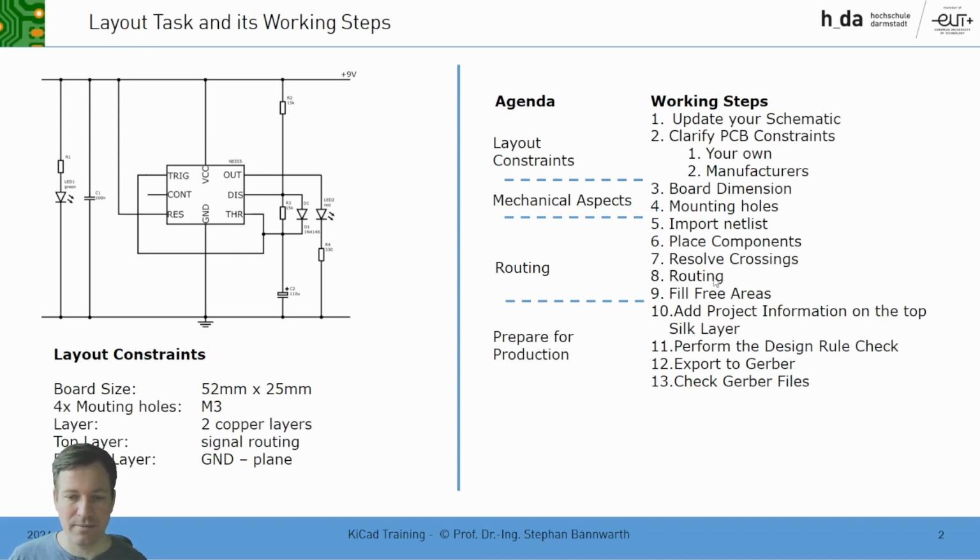We perform the routing. We have to make filling area. This means the areas where you don't have traces can be etched away completely, but this is very expensive. That's why you put copper islands, and on the one side, it's a cost point. On the other side, if you have these islands, you also can put them to ground or power supply. So you get some shielding of your signals. So we will make these filling areas.